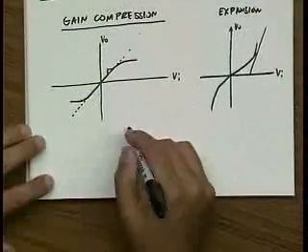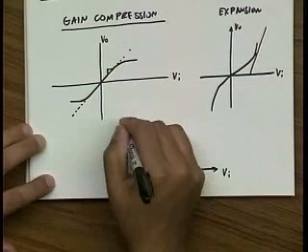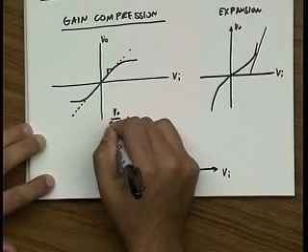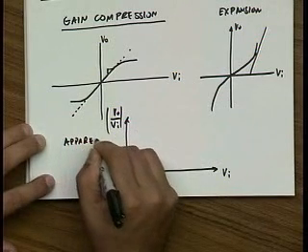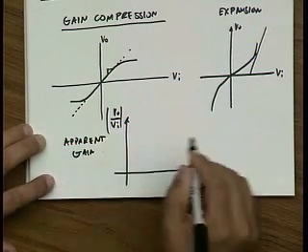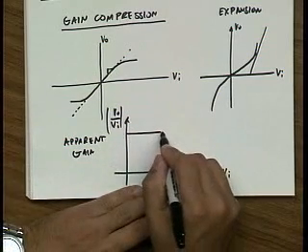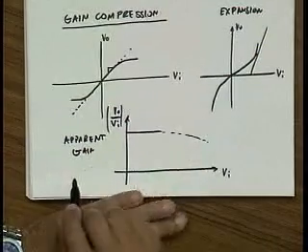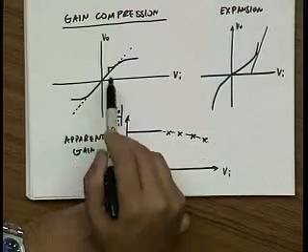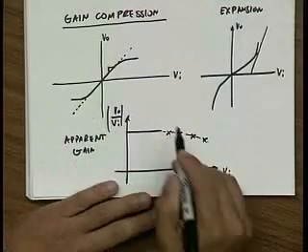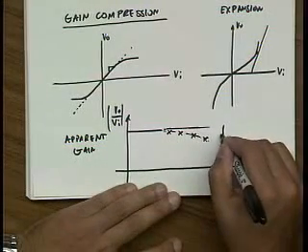So if we look at the apparent gain as a function of the input, let's say this is the input signal, and this is the output signal over the input, we'll call this the apparent gain. Then at low amplitude this will be very constant, but at high amplitude it'll basically fall. So if we take data points like this, if we look at the input-output relationship from here and just plot it, we find that the gain drops. So this is called gain compression.